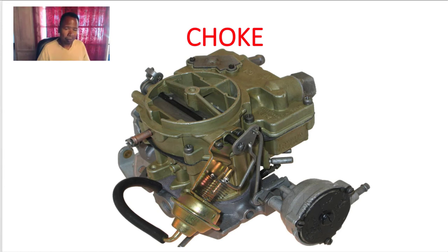As it starts to warm up, this thermal spring in here is also hooked up to the choke through a lever going this way. Heat is coming in from this tube here. As it starts to heat up, it's going to relax and open up this choke right here. It's also called a choke spring. And I should have said, the reason it's closed like this is because this choke spring is closing it. There are adjustments for it. In the middle there's a little adjustment right here, and a little notch on this plate right here. So when it's cold, this spring inside is closing this.